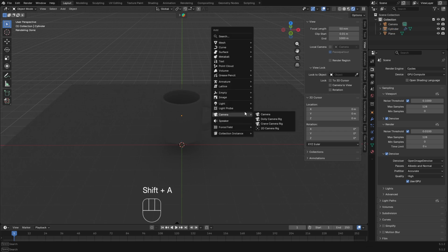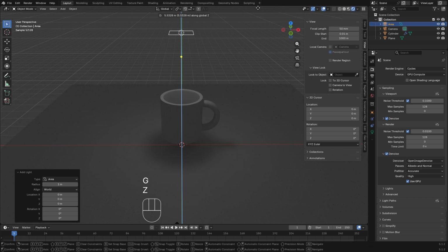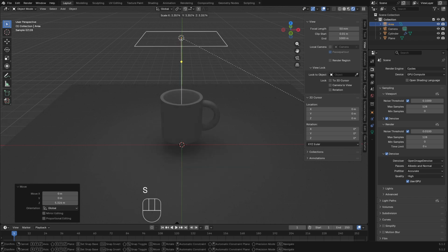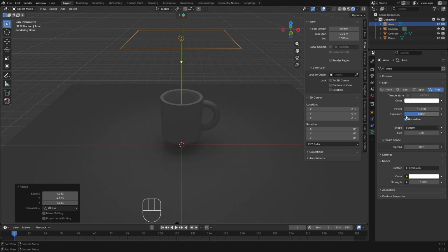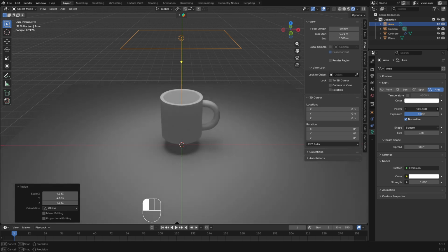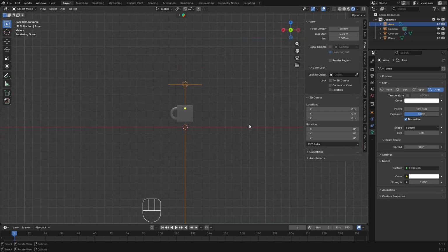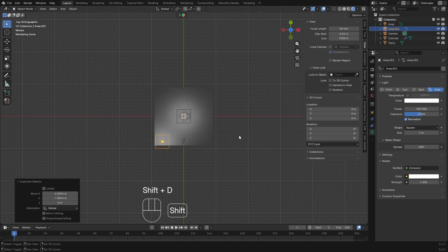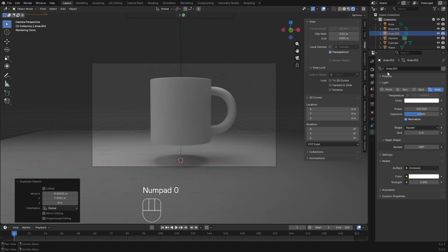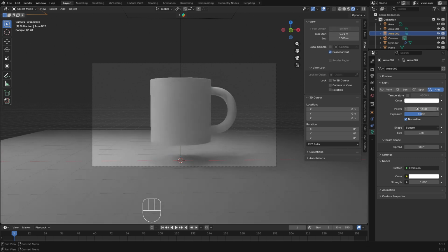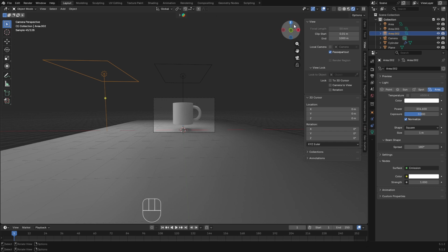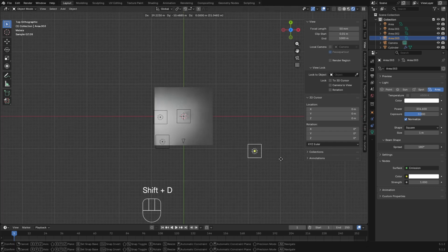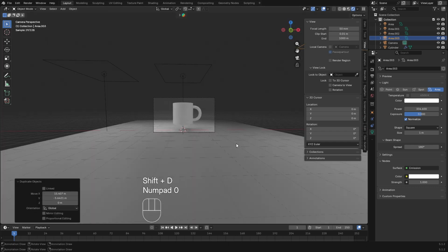and then render mode, add an area light. Drag the area light up on the Z axis and increase the power, and then Z axis, Shift D, duplicate the area light into two spots, then increase the power of your view and then adjust the light again.